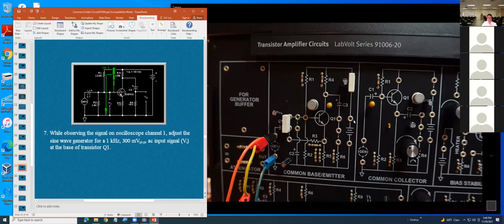What if you had a more negative DC than positive DC? There won't be any effect in the circuit, just your measurements at each component will be either positive or negative, correct? Depending on the circuitry. For this circuitry, they must be positive. That's because of the direction of the arrow in the transistor and how the current is supposed to flow, to ground.